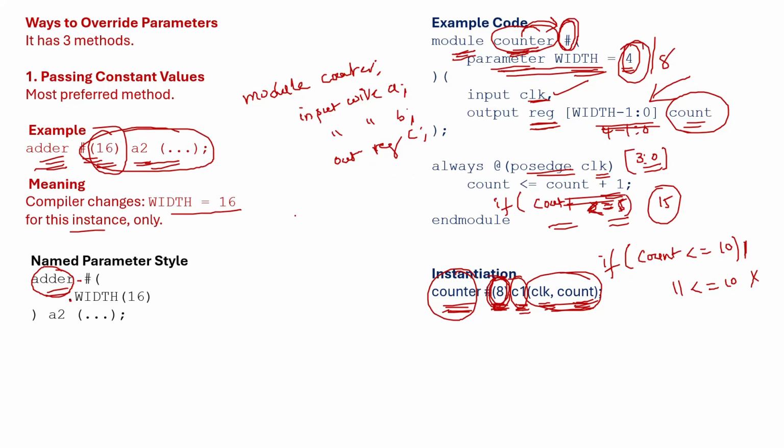Okay, how do you instantiate your module in your TB? Just take the module name. What is the module name? Counter. Take the same counter and then a user-defined name, DUT. Inside that, dot A of A you are mentioning. Okay, that is the name based instantiation, right?